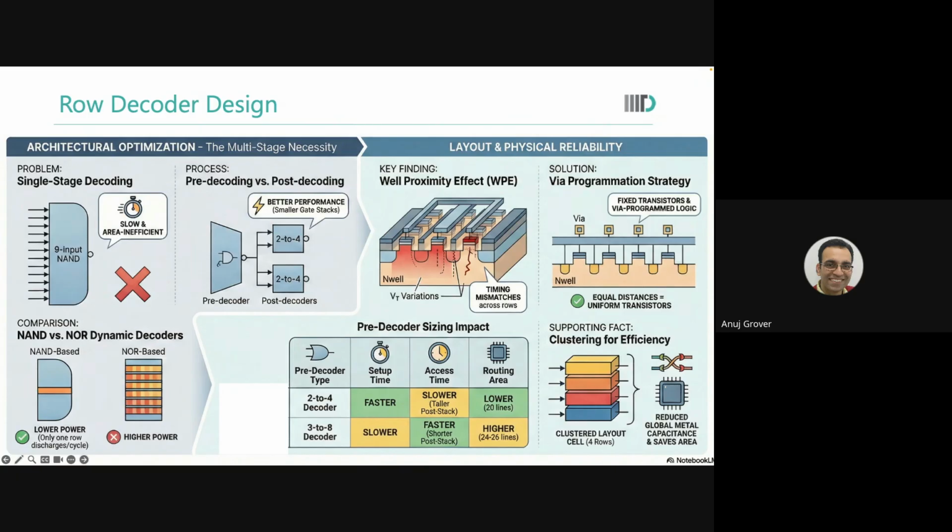So this zeroth output of this decoder was going to all of them. Are you with me? So the zeroth was going to all of them because you had to select row 0, row 1, row 2. And of these three, 0 was going here, 1 was going there, 2 was going there, and so on. You do realize this NAND gate had exactly the same set of inputs for all these four rows?